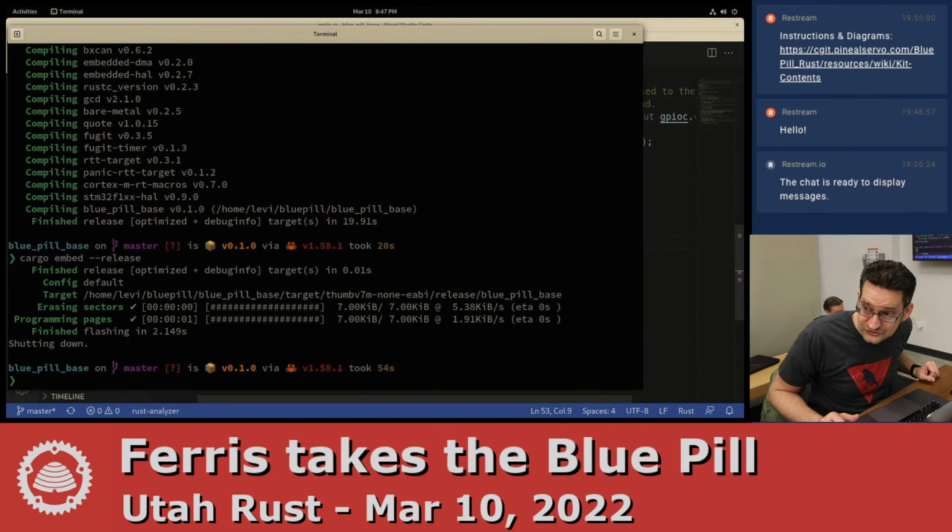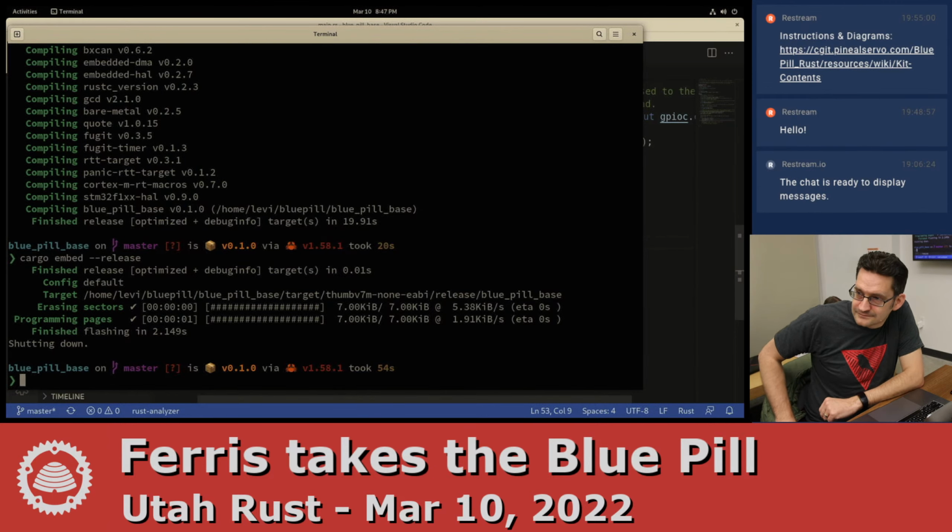So I had a question about the exit. When this thing panics, the last step is that it sets the pin to low, and then it crashes. So the release on is low. Yes. It's an active low signal. Okay. I have a bunch of resources in the wiki that talk about different I/O signal stuff and the difference between floating signals and push-pulls and active high versus active low.